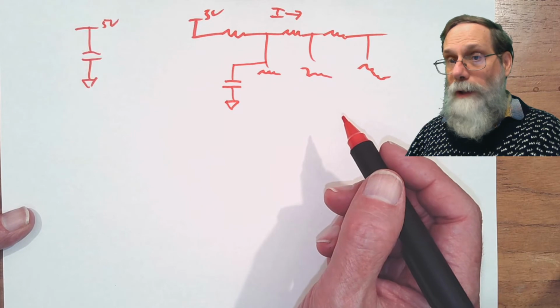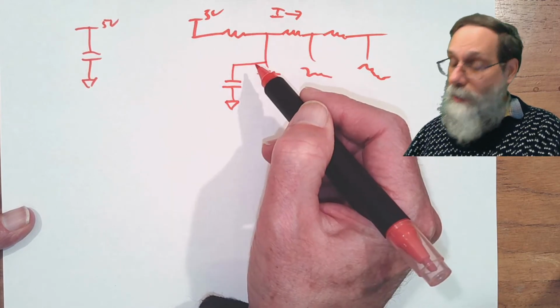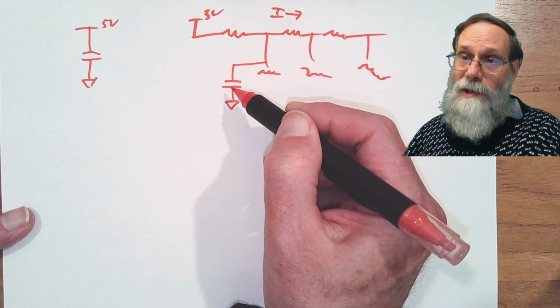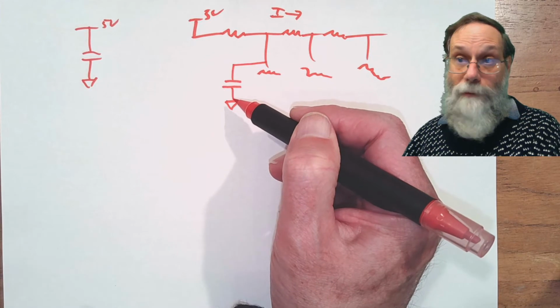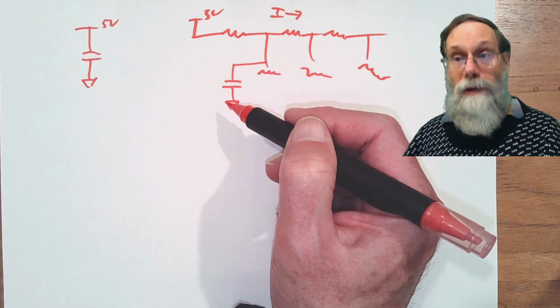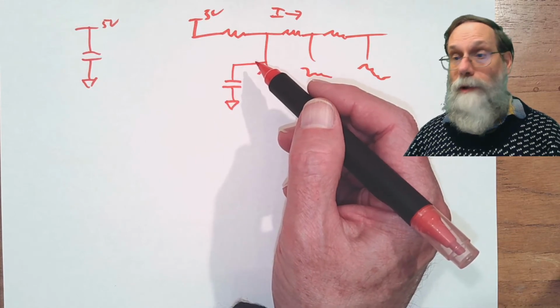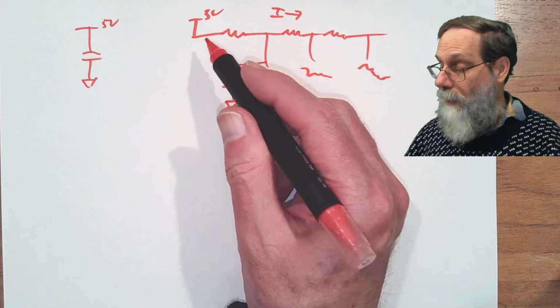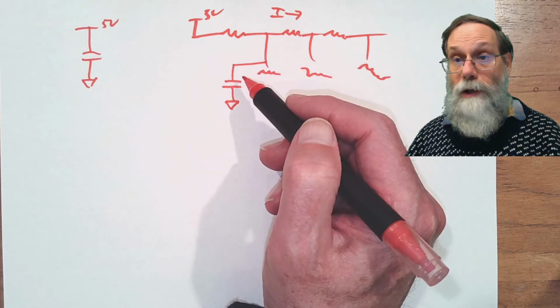And this does two things. One is that when you've got this fluctuating voltage here, the capacitance passes some of the fluctuations through to ground, shorts it out, at least if it's a high enough frequency signal. This is a very low impedance here, and so the signal gets attenuated. The DC doesn't change, but the higher frequency stuff gets reduced substantially. You've got essentially a low-pass filter. So you reduce the noise coming in.